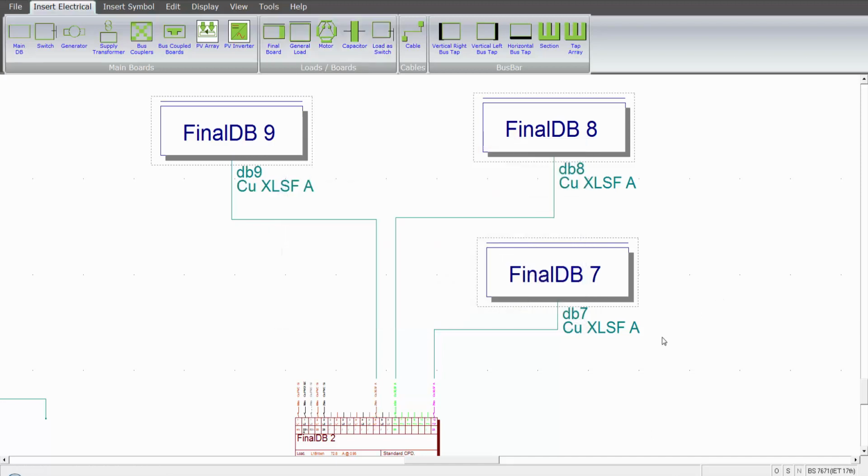And again, you can go into the boards and set them up as you would do normally. You could have set the boards up totally in isolation and set all the circuits up individually and then connected the cable in, making sure that the appropriate phase arrangement is set up. So we've discussed 3 different types of board: a single phase, TP&N, and a TP.